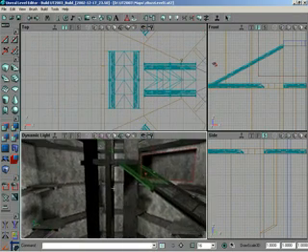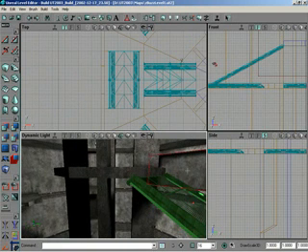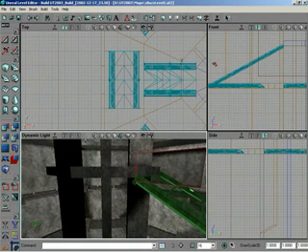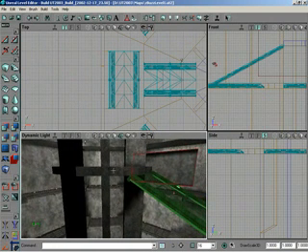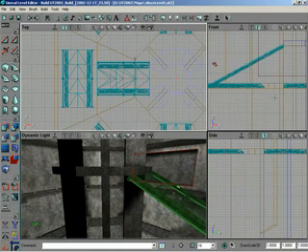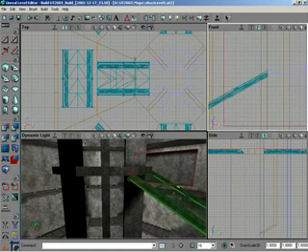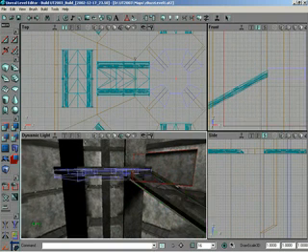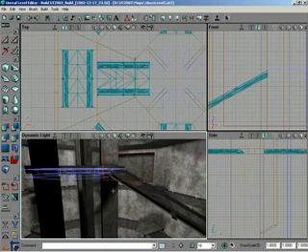Now let's see how close you were on our center ring up there. Not too bad. Not too bad at all. Okay, so let's see. I could move it down, and while I'm at it, I'll rebuild lights and geometry, so I can get an idea of how the shadows are working. Let me go back to where we added that ring brush. Select it. I can simply Control-drag it down, and let me do a quick rebuild all, so we can see what we've got so far.